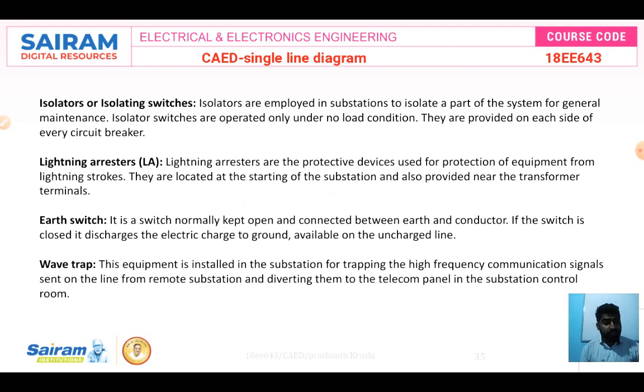In the circle there are lamps, right? Like street lamps. At the top we have street lights in the circle. You can check there is a cone-like pole, a rod-like structure they kept, to avoid, if lightning appears, it affecting those lamps. If you are not using those lightning arresters, sometimes the whole lamp system will be damaged. Otherwise, it will even melt if you are not using them. So that is the purpose of having a lightning arrester in the power system components.